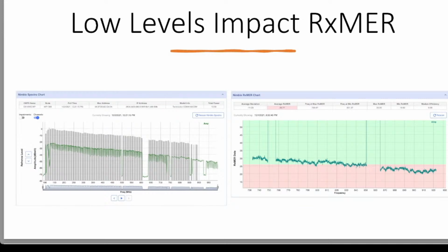The graph on the left is showing all your single carrier QAMs, your OFDM, but it looks like linear tilt or even non-linear tilt, but doesn't look like roll-off. Correct. And I looked at the subscriber's home around, and they did not have this tilt. So I almost think this subscriber must have an in-home amplifier or something like that. It just had nice linear, it's beautiful linear tilt, actually. It's really horrible performance for them from a data standpoint.